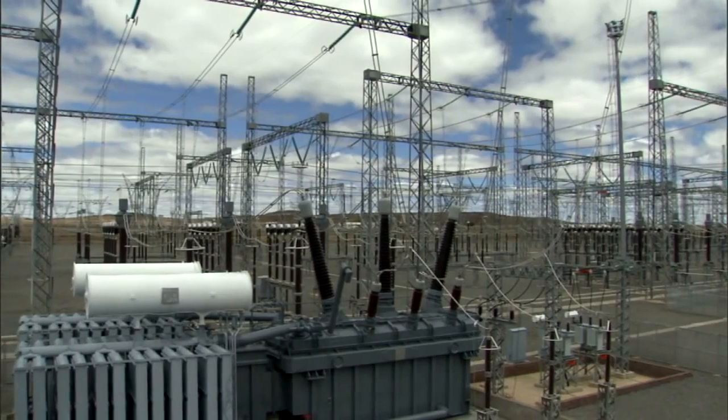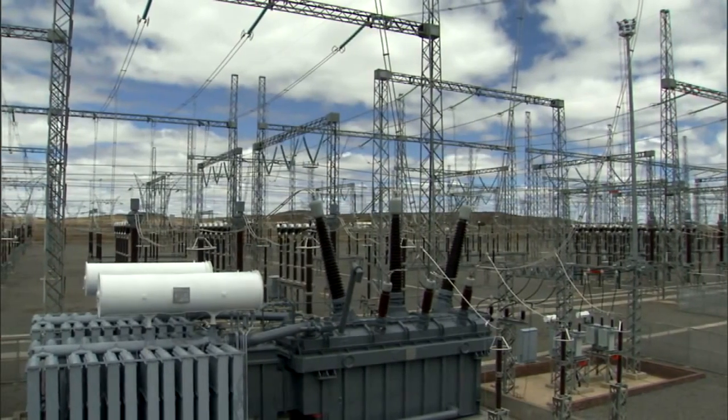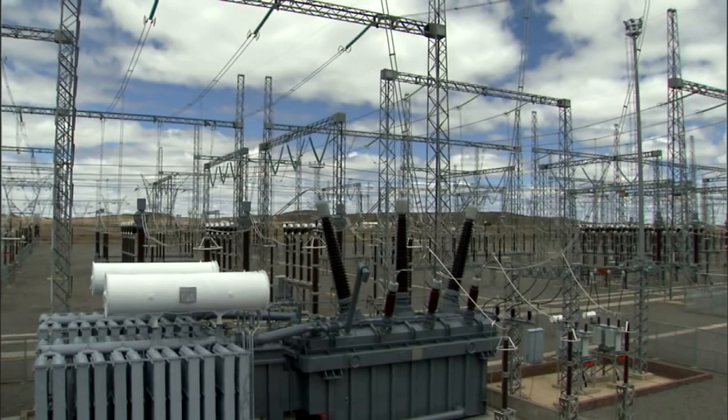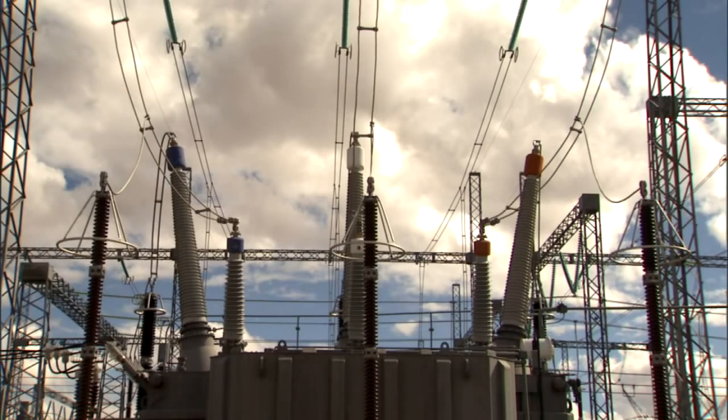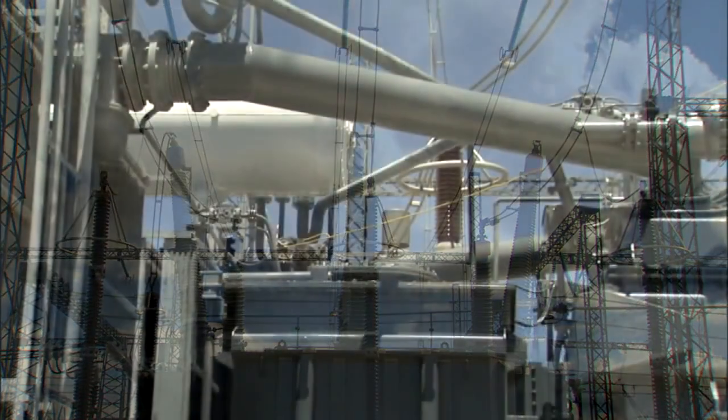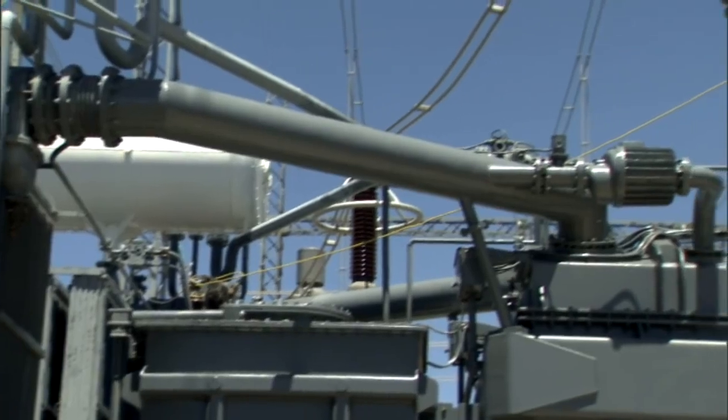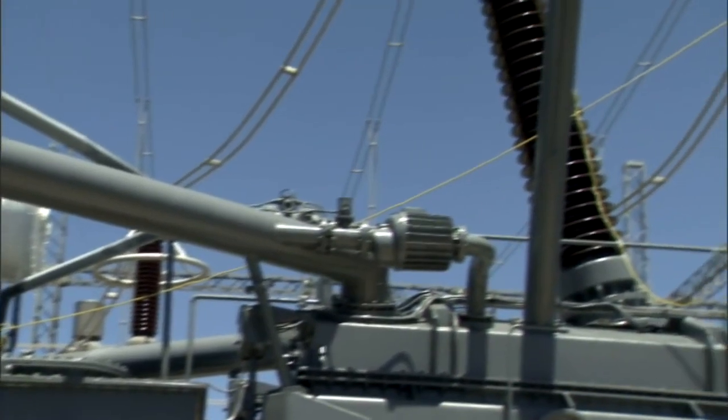The level of dissipation can increase due to a number of factors: through aging of the insulation, due to the ingress of water into the insulation, or as a result of partial discharges. Measurement of the power factor or the dissipation factor is an important diagnostic tool to assess the quality of the insulation.